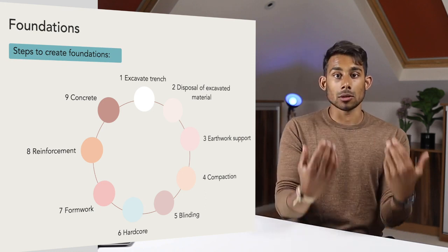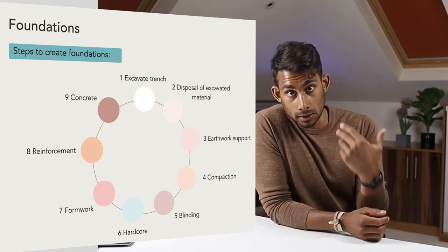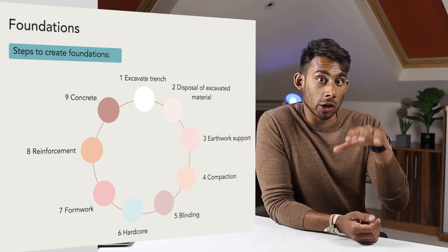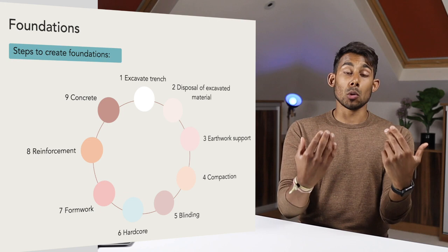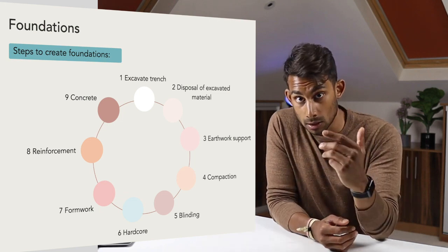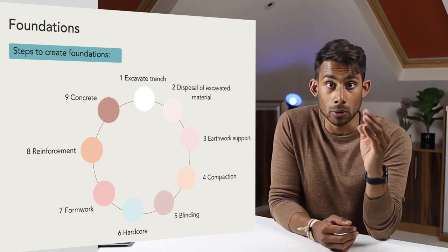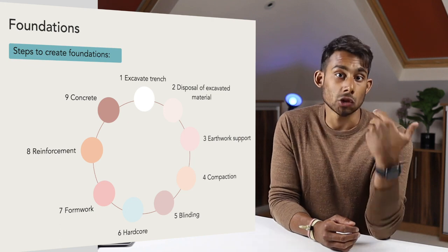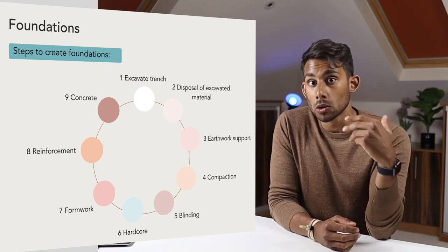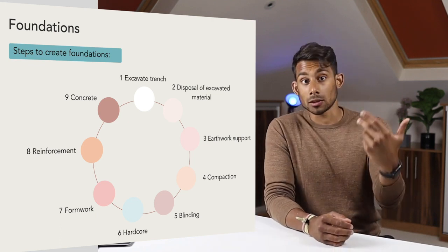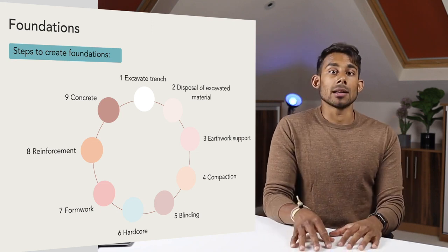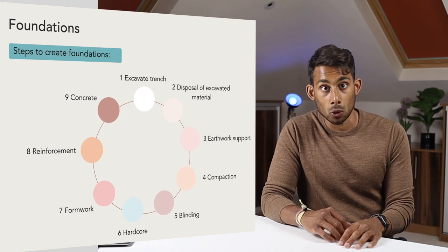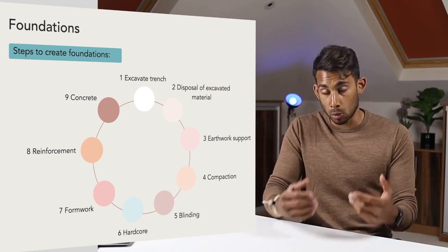It is not advisable to lay concrete in any adverse weather conditions, but if it is unavoidable, there are a few things to consider. The minimum air temperature to pour concrete is 3 degrees Celsius, to make sure that ice doesn't form within the mix, which could compromise the strength of the concrete. You should also never pour on top of ice or frost, so if this looks likely, protect the subbase with insulating blankets or thaw with heaters before the pour.